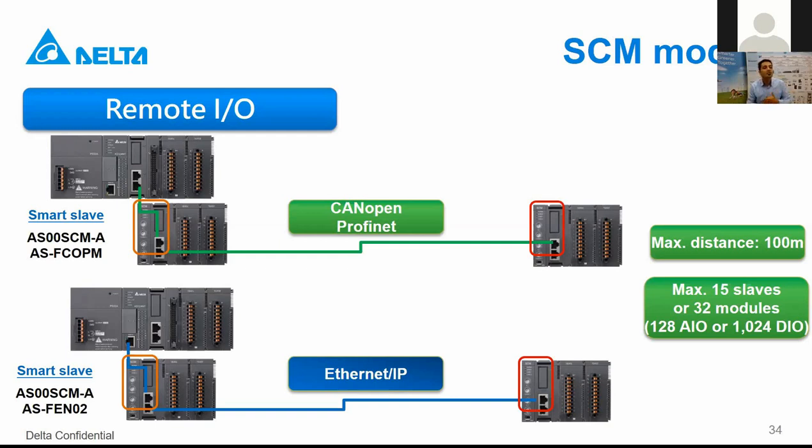But I can say that it's going respectively. So I mean, let's say that you have one input here, which is the X0 channel, right? So the other input is in the remote I/O, and then it goes with X1, and the second one goes with X2. So it's going respectively. But it's also possible to check in the hardware config. Okay, I hope that answered your question.